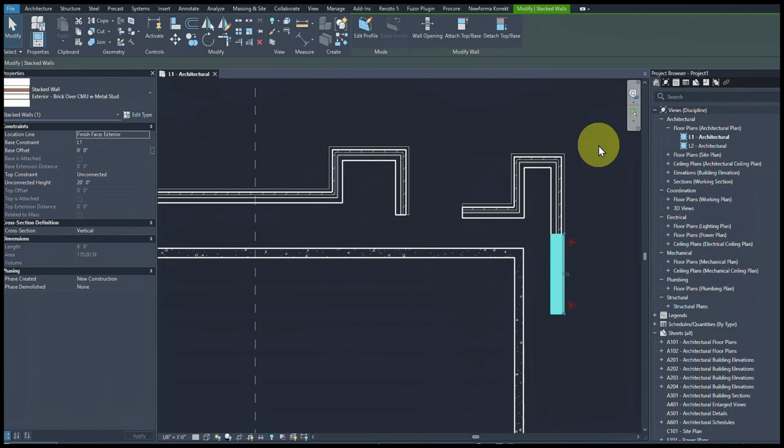So you guys see how that line is going to help you maintain a proper thickness or the boundary of the area that you draw. If it's a building and you have an exterior wall, if you want to change the thickness of the wall, it's not going to grow from the outside, it's going to grow from the inside. If you have a wall center line, it's going to grow on both sides, which is going to change the perimeter of your building.